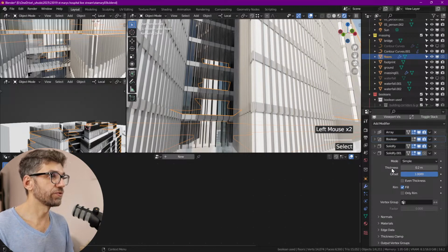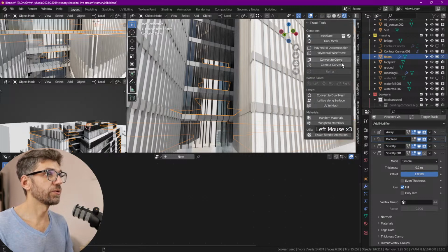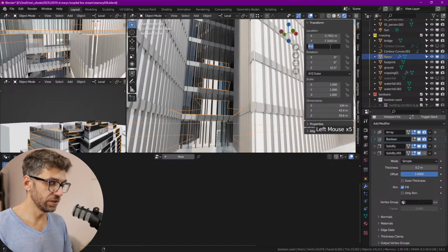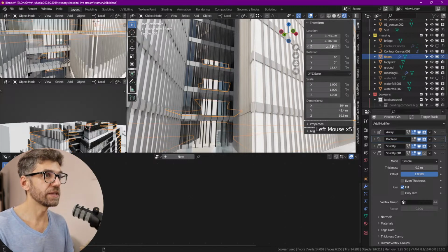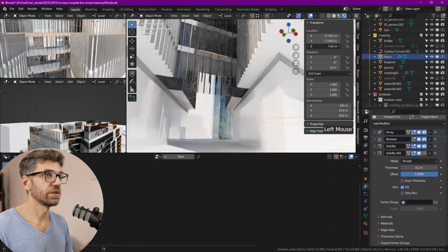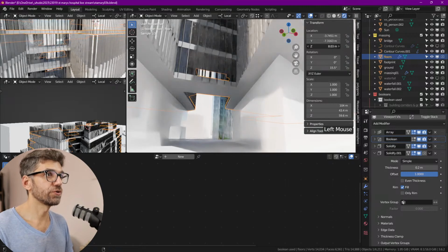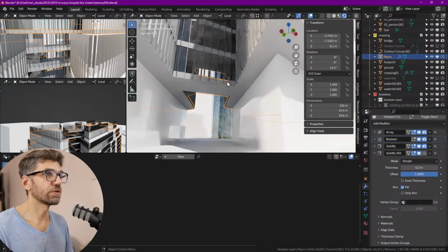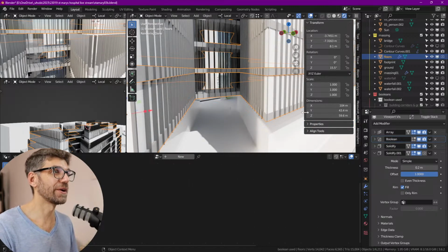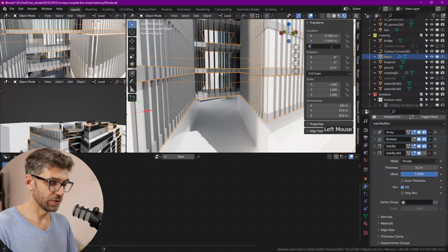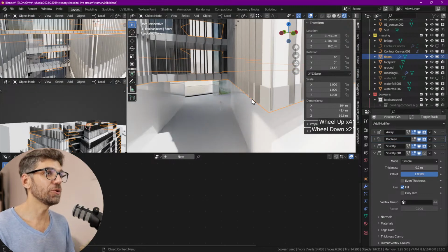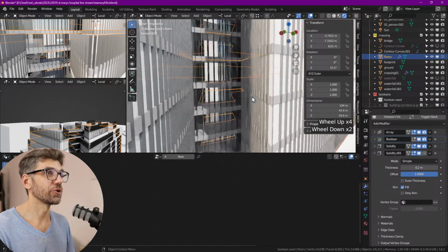So now I've clicked on the floors. Let's look at their location to make sure that they're in the right place. So they're at 8 meters, indeed. Maybe we need to try something like 7.8 meters. Is that showing up? Not quite. Oh, it's coming through. Oh, okay. So it needs to go slightly higher. There you go. So that bridge, it didn't have a bottom. Now it has a bottom. So maybe we can go to something like 8.01. Yeah, so as long as it's a little bit higher than that top point, then we're good.